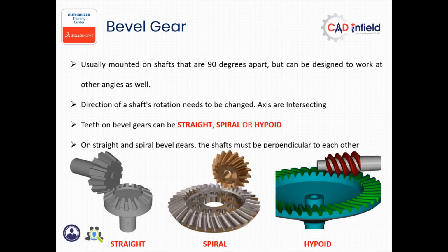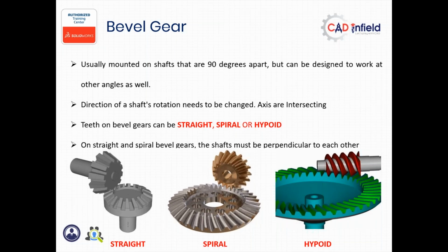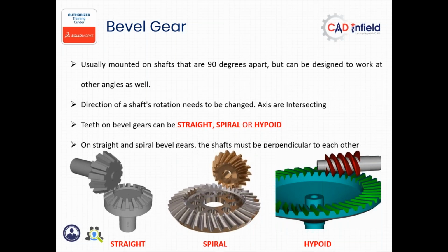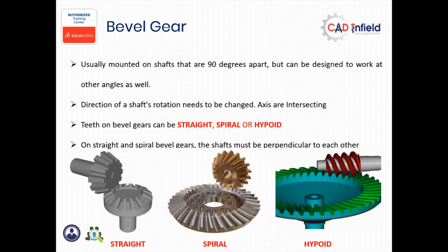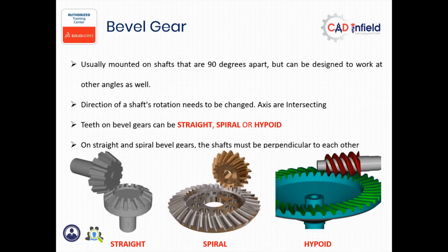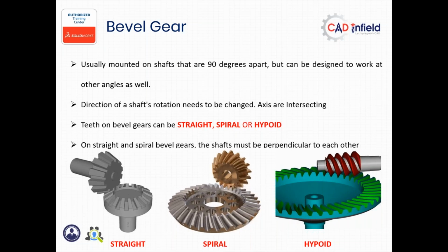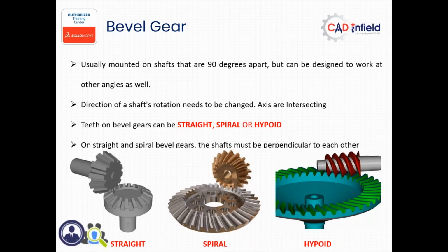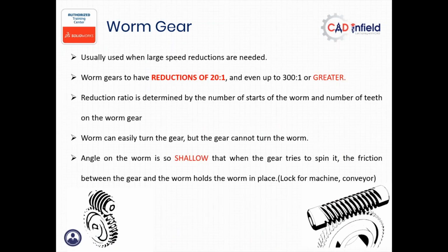So for a straight cut, we have a challenge. But for an inclined cut, the inclination is always given, so due to the inclination it will be able to engage multiple teeth at the same time. The same logic is also applicable here, for straight or spiral. And hypoid is a little bit in the family of worm. It looks like the same kind of thing, but let's not depend on that. This is very important, that's why I marked this in your notes here.